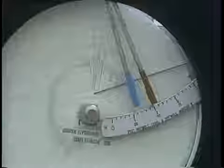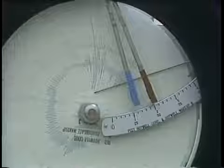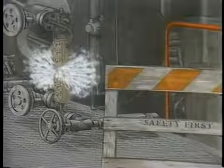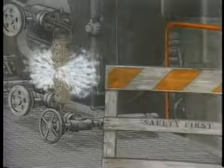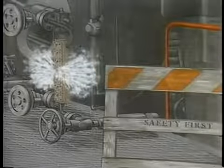The boiler can then continue operating until it is convenient to schedule a shutdown. This being the case, the operator must isolate the area around the leaking gauge glass and inform supervisory personnel of this abnormal condition and the need to schedule the unit offline. If neither of these choices are possible, then the operator must take the unit offline immediately. Regardless of whether a boiler leak occurs inside the boiler or outside the boiler, the operator must make a decision as to the appropriate action to take.